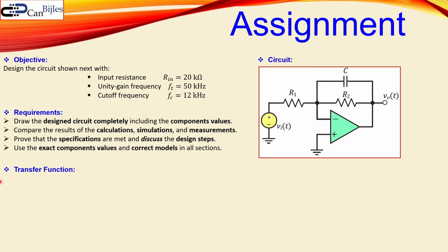Okay, let's start directly with the mathematical expression, which is our transfer function for this circuit, because we go from VI input to the VO output. So we can have the transfer function here in the Laplace domain, which is given by HI, which is for integration, and S for the Laplace parameter, which is then minus ZA over ZB. Why minus? Because this is an inverting integrator. And the ZA here is the parallel combination of the R2 and the capacitor C. That's shown here, the first one, so the R2 and the reactance of the capacitor C.